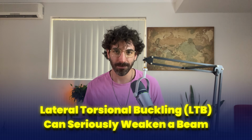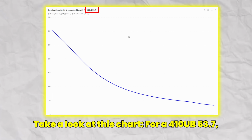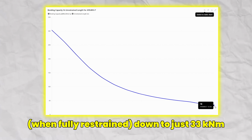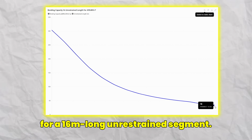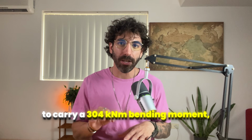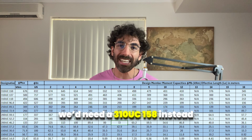Lateral torsional buckling can seriously weaken a beam. Take a look at this chart for a 410 UB 53.7. The bending capacity drops from 304 kNm when fully restrained down to just 33 kNm for a 16 meter long unrestrained segment. That's a massive reduction in capacity. What does this mean in real life? If we had to design a 16 meter unrestrained beam to carry a 304 kNm bending moment, we could not use the 410 UB. We would need a 310 UC 158 instead.